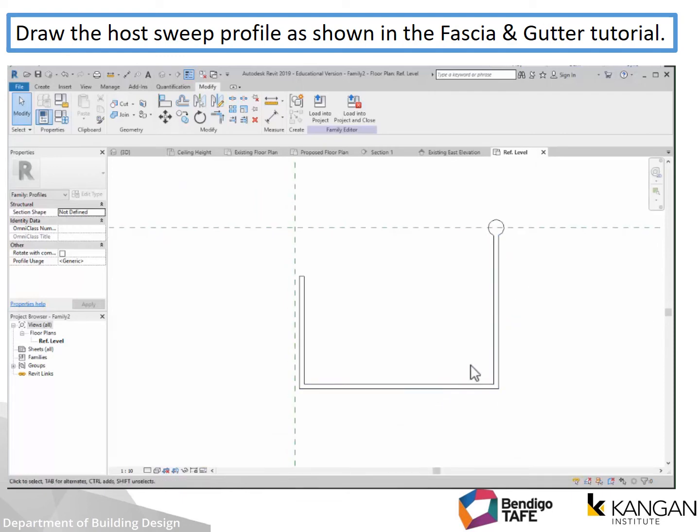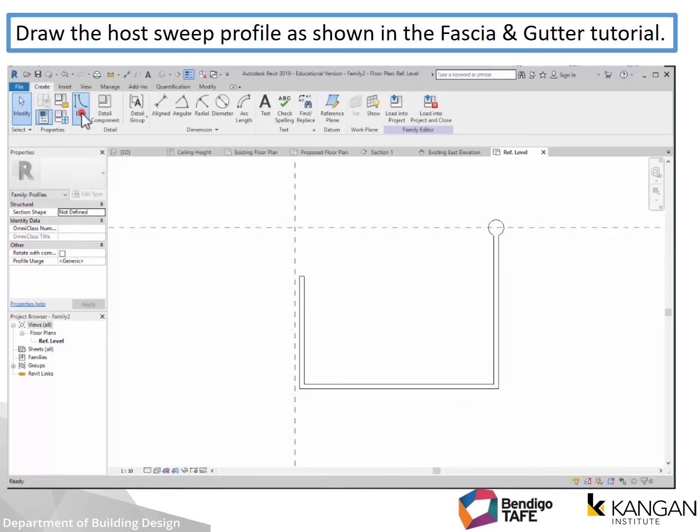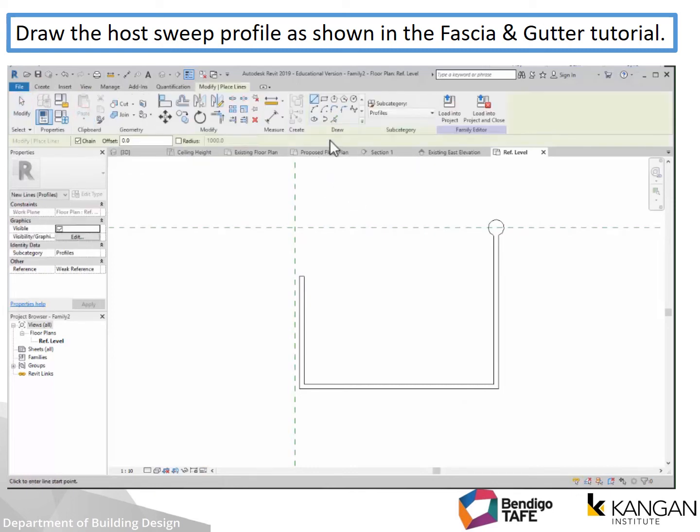So getting the arc for this quad gutter, there's a handy little tool that we can use. In your drawing of a line, we can use this little button here. It's called a fillet arc. Let's watch the video. Hopefully the video works on yours. So we'll pick on that fillet arc, and I'm going to select the very bottom line and the very outside line, and as I bring my cursor backwards and forwards, you can see there that it's giving me a radius.